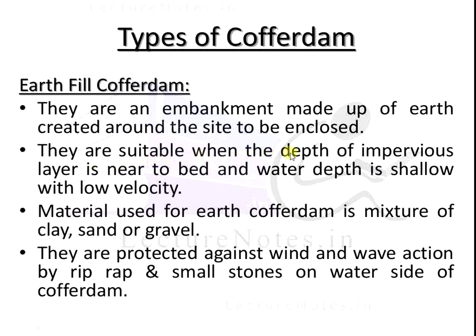They are suitable when the depth of the impervious layer is near the bed and the water depth is shallow with low velocity. The materials used for the earth coffer dam are a mixture of clay, sand and gravel.